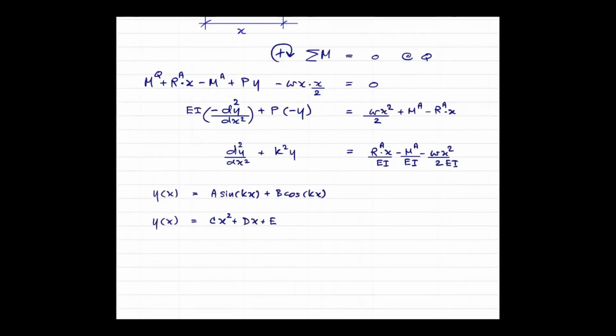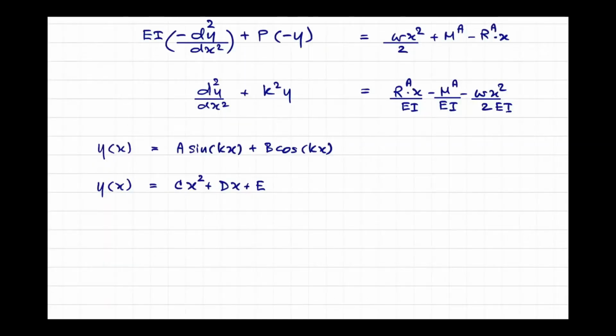Other kinds of tests that we can do is dynamic testing in the lab. Even if it is reverse cyclic or the gravity load, the rate of loading is very slow, quasi-static. Okay, we call it quasi-static testing. But we can also conduct dynamic testing, generally in the real structure, in the field, like the bridge, like the building. That kind of dynamic testing, we don't bring our structure to the collapse, to the real failure.